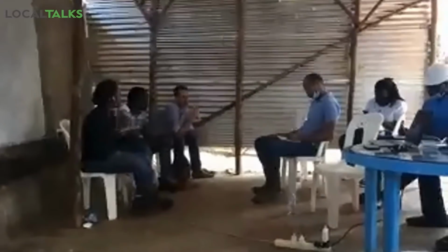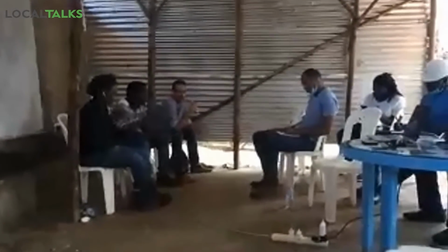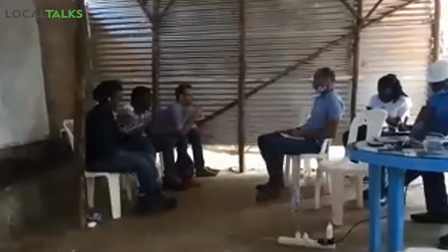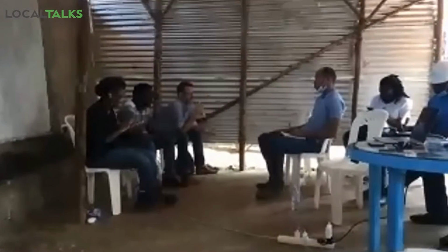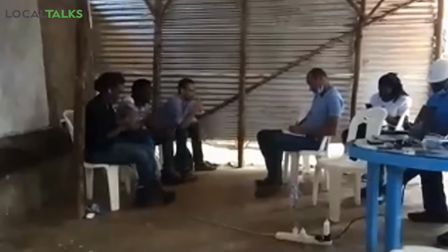Edson has explained during the presentation the triple protection of moisture from below. Triple in the sense that we first of all have a stone foundation, which in itself has no capillary action at all. We have a very dense, thin but very dense concrete slab over it. We also have a damp-proof membrane below that.